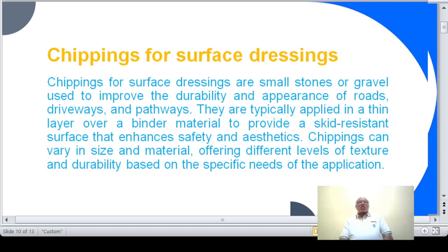The effect of dust can sometimes be mitigated by damping the chippings prior to spreading them on the road. The chippings dry out quickly in contact with the binder when cutback bitumen or emulsion is used, and good adhesion develops more rapidly than when the coating of dust is dry.